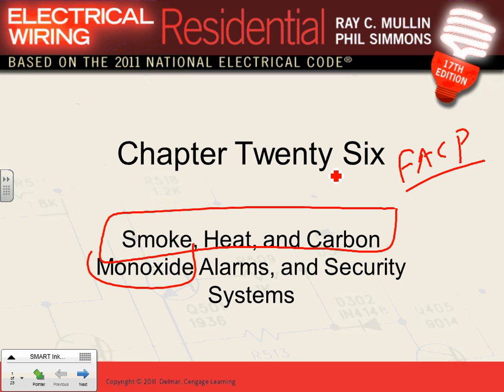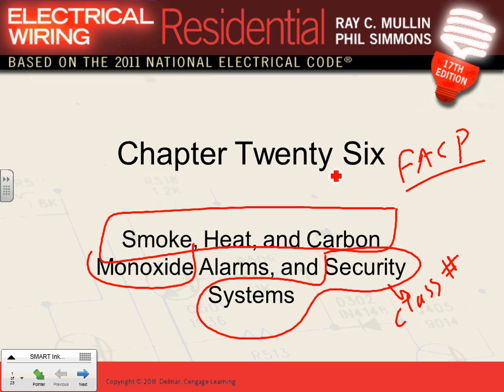Okay. The second system that we're going to talk about, guys, is your security system. Your security system is called Class 2. Class 2 circuits, these are power limited circuits that you use for security systems. For example, you're going to have a keypad where you're going to program the security system. Somebody breaks the glass right here. You're going to have a glass break detector. It senses the frequency and sends the signal, turns the horns on.